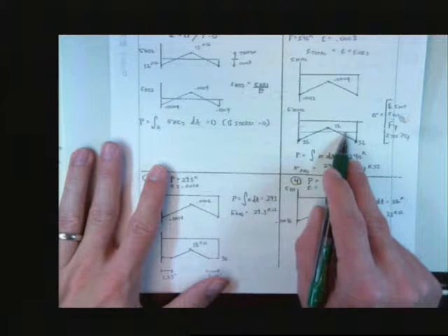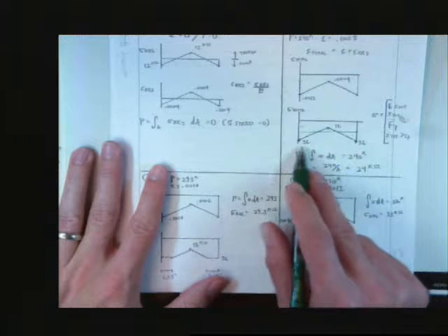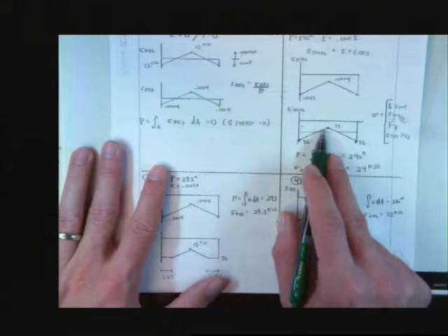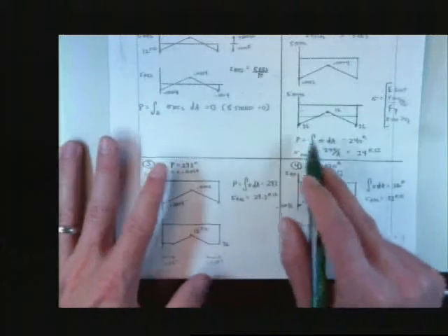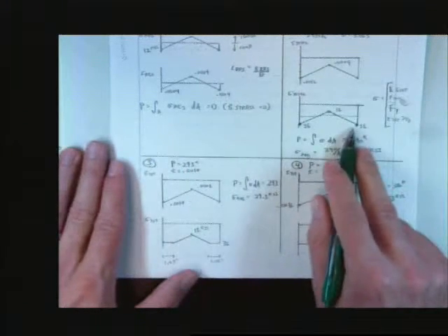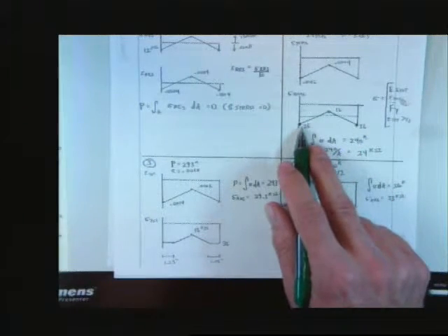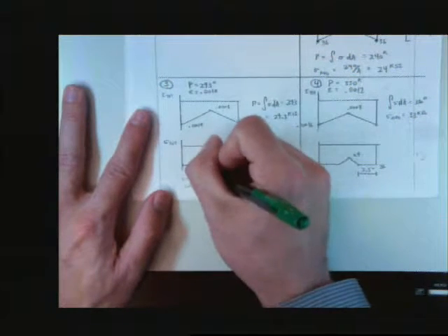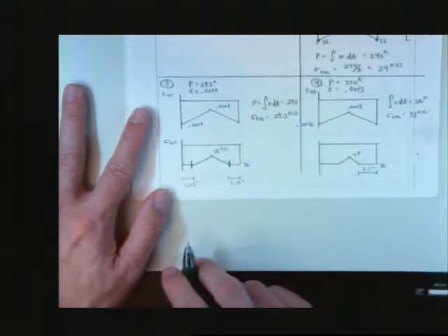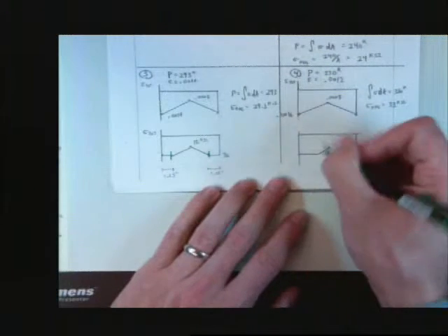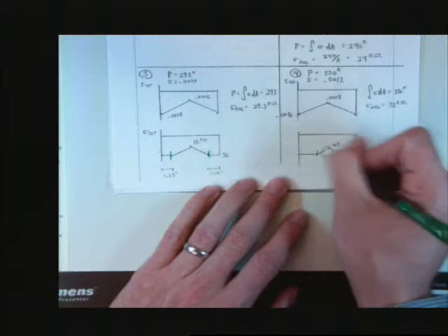It just so happens that never happens in real life. You have some points that are higher stressed and some points that are lower stressed because of residual stresses. And as you start increasing this more and more, this point starts to hit the residual stresses. First, it hit this point where the residual stresses plus the axial load causes it to start to yield. Well, what's that mean? As we keep increasing the load, that means that stress cannot go any higher. It stops right there. As we start increasing the load again, the stress goes higher, but that part's not.